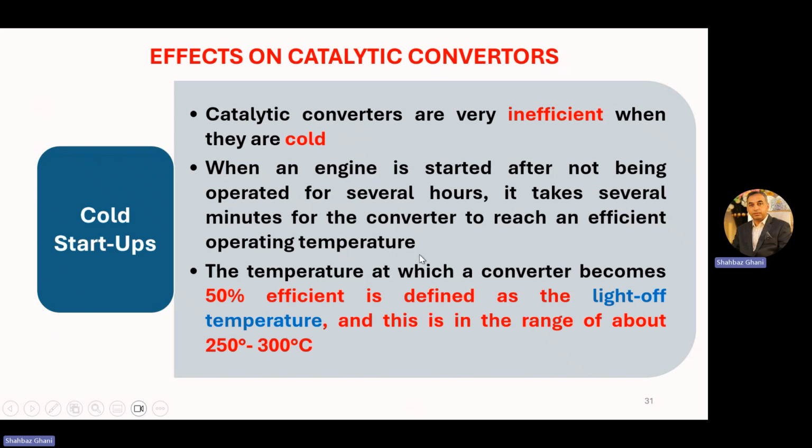So everything has to be at its operating temperature. Here comes one term which I use, NOT, N-O-T, normal operating temperature. Every equipment, every mechanical device has this NOT. If you are sitting in a vehicle and you start it, do not quickly put it in gear. You first maintain the temperature. Maintaining the temperature is basically achieving the normal operating temperature. Then you put it in gear and move the vehicle. So the same case here.